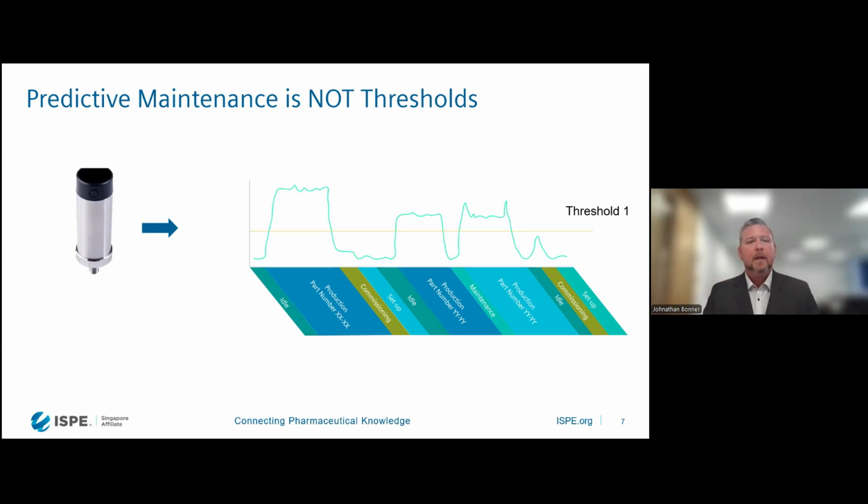So with the systems in question, these threshold-based companies will come in, install sensors, and possibly even set up some thresholds or limits for you. These could be based off of ISO standards, the size of the motor, the bearing type, the rigidity of the base and mounting. But there you have a simple threshold limit. Well, it is missing all of the important detail, especially around the operational complexity that you have. So maybe someone in your team needs to go and reset the threshold.